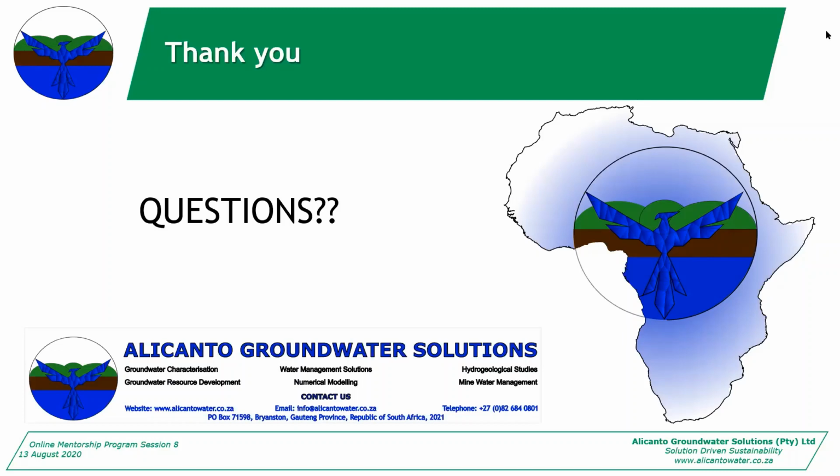Well, look, your big 3 are always going to be recharge, conductivity or transmissivity, and then your storage. Those are the big three. Those are the ones that you fiddle with first. Recharge, because we don't always understand the recharge at a site. You know, it can vary from one end of the site to the other end. So we fiddle with that one.